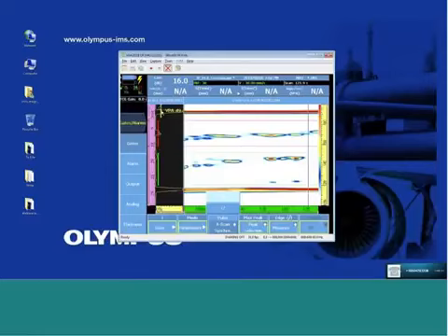So when I'm moving a big probe with a water wedge over a rough surface, I can ensure that my surface interface signal here is always at 0. That's also called a floating gate in an immersion tank applications.